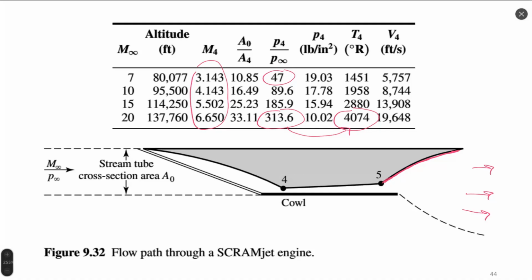Each reflection of shock wave after 0.4 creates disturbance in the boundary layer, which we will see very soon, and it also intensifies temperature and increases thickness of the boundary layer. And all these processes cannot be just ignored.